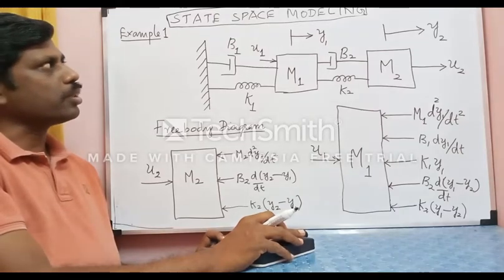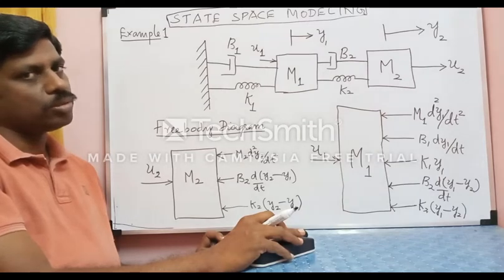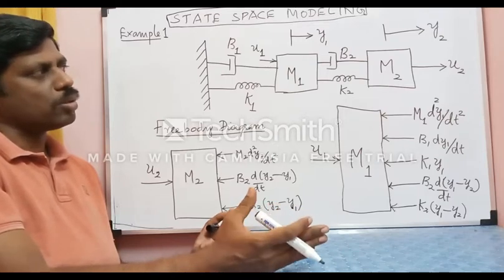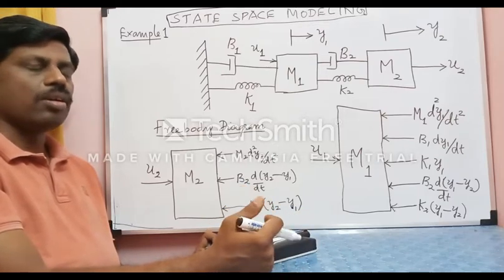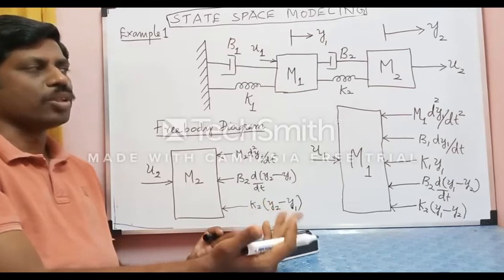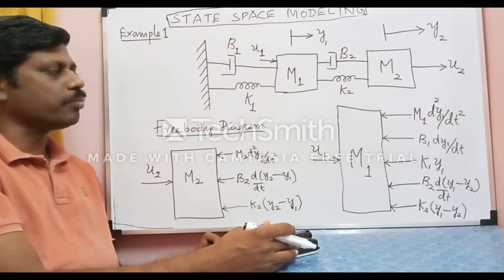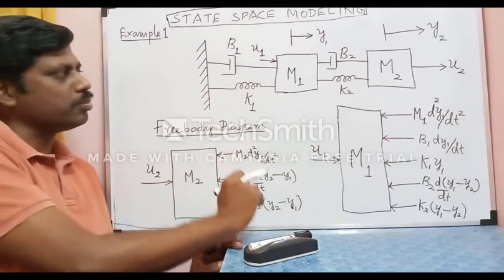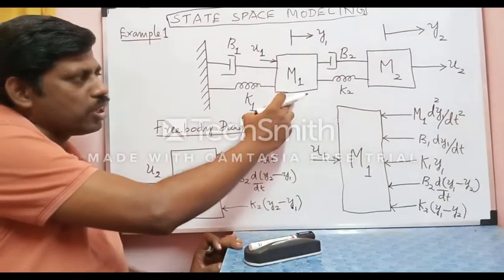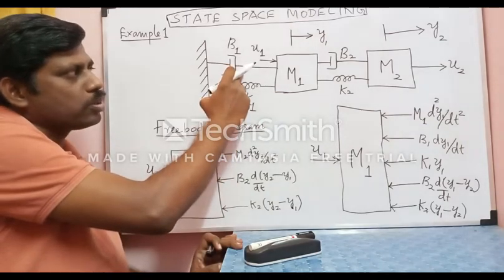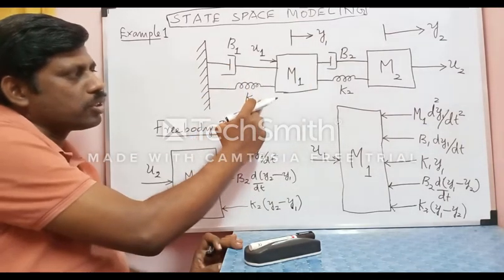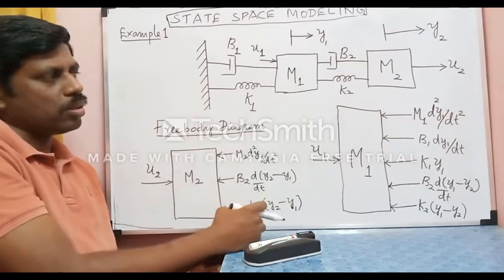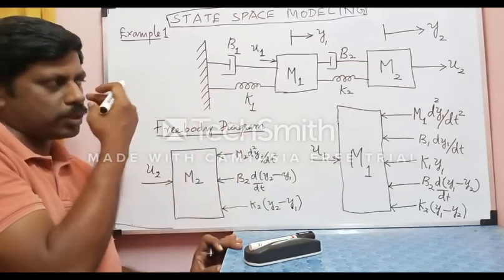So in this lecture, we will try to extend the basics we learned to slightly more complicated systems, systems with more elements, or higher order systems. Okay. As a first example, I've taken this system, which has masses m1, m2, the dashpots or dampers p1, p2, and the springs k1 and k2. Of course, this has more elements than the system we considered earlier.